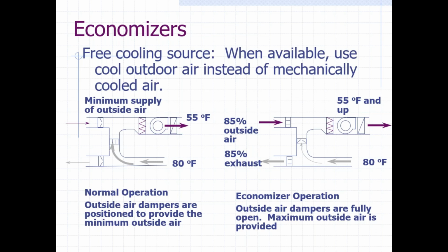The problem we have with economizers is they usually don't work. Someone said at a conference recently, which I thought was hilarious, that economizers are a great invention, except they've probably wasted more energy than they've saved. And I think he's probably right. You can walk into almost any building, assuming they've got 4 or more air handlers, and you know they've got economizer issues. You just know, because they always do.